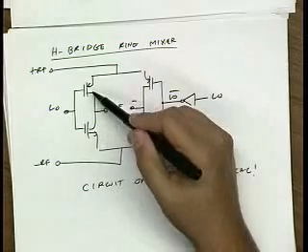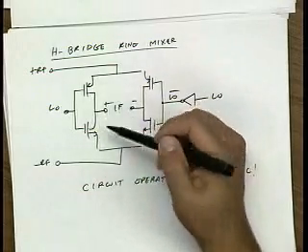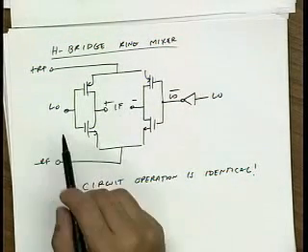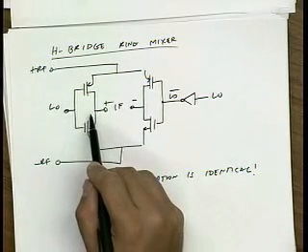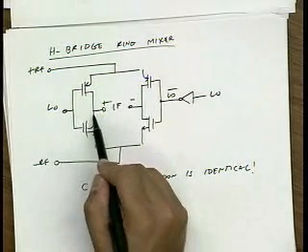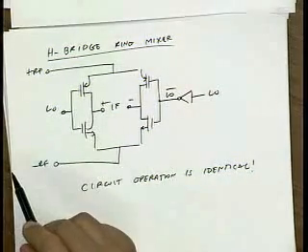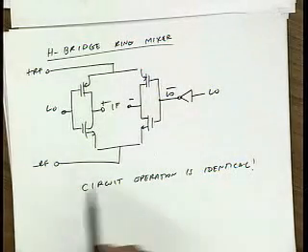Flip the order, so put the NMOS over here. No, because then it becomes a Class AB driver stage, right? So then it would take the LO and basically the output would be like a follower. So when the LO is positive, the LO would appear at the output. So we don't want that. We want the LO just to control the on resistance of these devices. Okay.